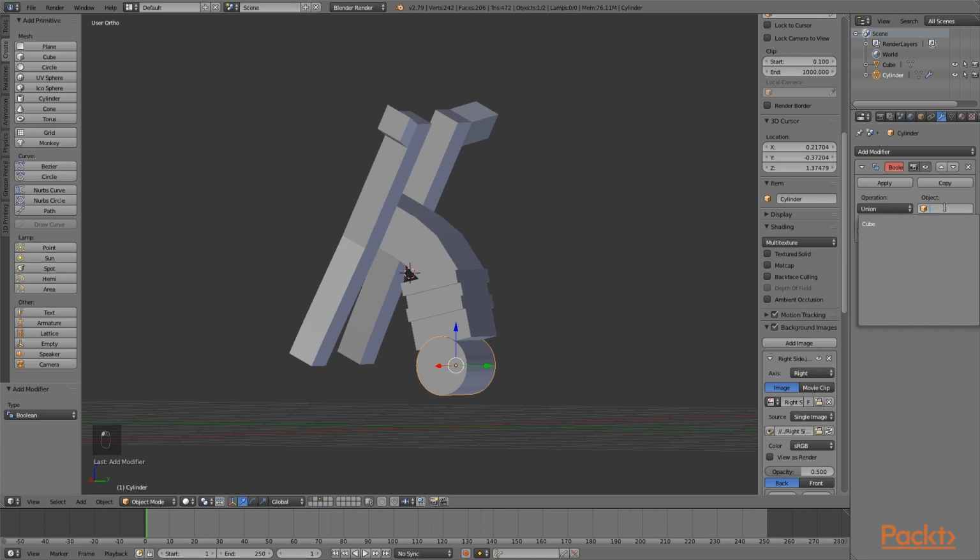So I can click this, and our cube's the only one in here at the moment. If I wanted to select the cube, I could come over here and just click around. So I'm going to select the cube, and bmesh is the best way to do this. There's a carve, which is another algorithm, but bmesh is the generally used, the default, and that works fine. And then you can click apply.